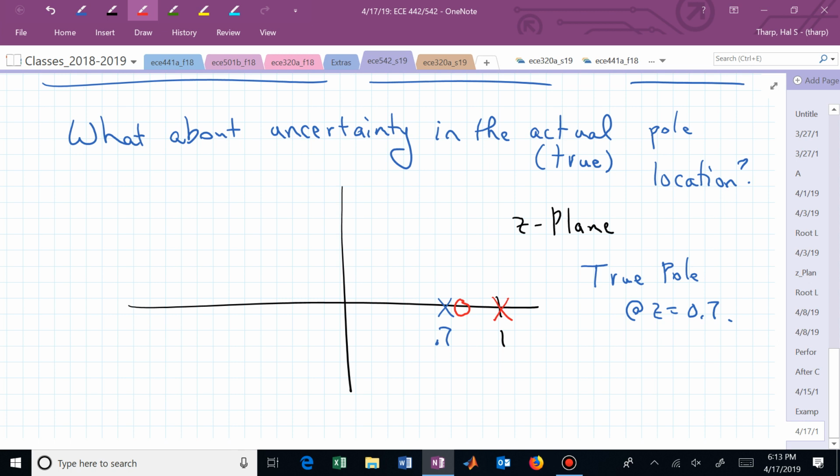Hopefully you can see that one piece is associated with the pole at 1, moving to the controller zero at 0.75, and the other piece of the root locus is taking off from the actual pole at 0.7. Now if you gain up the system with the gain that we picked, whatever it was, we picked it equal to 1/2, but let's just say we picked the gain K.